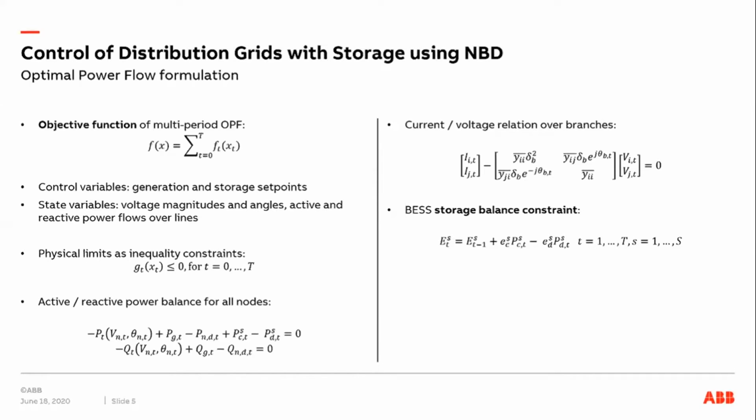Exploiting the symmetry of the model, the matrix component with the subscript II is equal to the component with the subscript JJ, and in the same way, the component with the subscript IJ is equal to the component JI. Those values arise from the longitudinal and transversal susceptance and conductance parameters of each branch. The equations that describe the double bipole model are used to model the active and reactive power flow through the branches, and those flows are used inside the node's power balance in the previous equation.